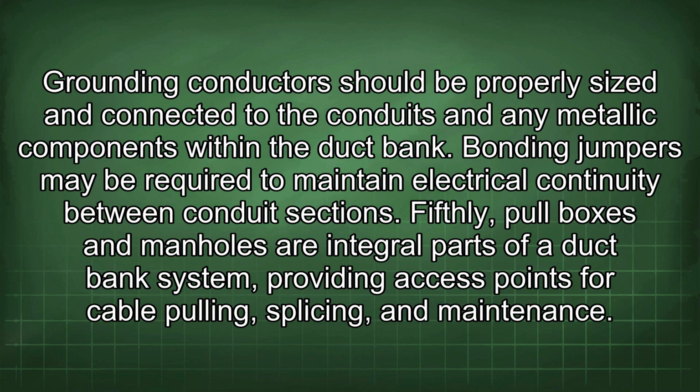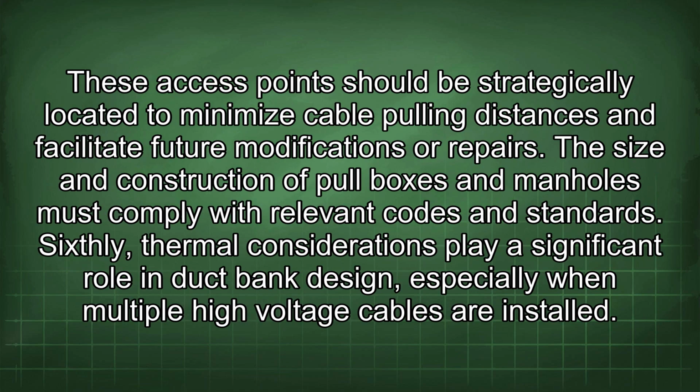Fifthly, pull boxes and manholes are integral parts of a duct bank system, providing access points for cable pulling, splicing, and maintenance. These access points should be strategically located to minimize cable pulling distances and facilitate future modifications or repairs. The size and construction of pull boxes and manholes must comply with relevant codes and standards.